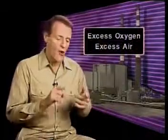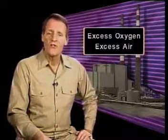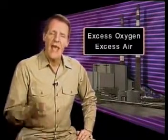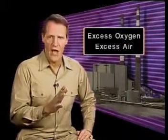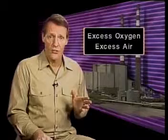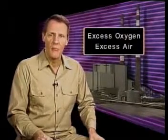We've used two terms that you'll often hear around the plant concerning the fuel-air ratio. They are excess oxygen and excess air. In many plants, there is a distinction between these terms. Excess oxygen is the term used to describe the oxygen going up the stack. Excess air, on the other hand, refers to extra air supplied to the wind boxes above the theoretical minimum amount needed for complete combustion.